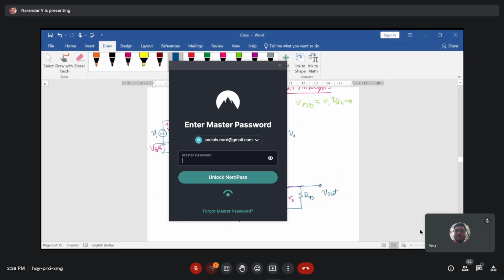So this is the small signal equivalent model for a resistive load inverter, by considering all DC sources equivalent to 0, right? For a small signal model, when you are designing an amplifier, there are three major parameters that we need to remember all the time: the gain of the circuitry, the input resistance of the circuitry, and the output resistance of the circuitry. These three parameters always need to be analyzed to judge the amplifier performance.